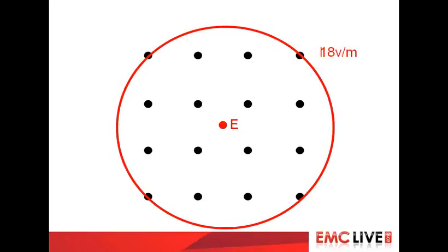So if we put numbers in there, we get 18 volts per meter. We can't be less than that, if you remember. We have to be minus 0 dB plus and a maximum of +6. There's a certain window that these points must fall in. So we've got 18 volts per meter there. The center point has to be between 18 volts per meter, cannot be less, and 36 volts per meter, cannot be more. But if we do the math, and again it's in the supporting note, we end up with 25 volts per meter. Now what does that mean in terms of our system design?